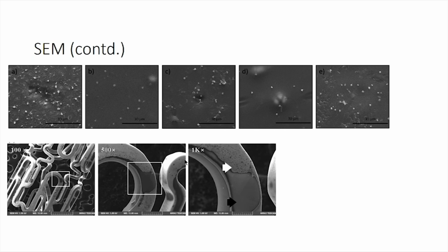There are 2 parameters which are important in microscopy, one is magnification and another is resolution. Magnification determines how much you can magnify a sample. Resolution determines how detailed your images are. Magnification depends on the instrument property, and resolution depends on magnification, but also on how detailed you can observe, because in scanning electron microscopy if I go above 10 nanometer size, the image will not be detailed. So, you have to go for higher end equipment. You will have that magnification, but you will not have a clear picture. So, resolution is very important when you are looking into microscopy.